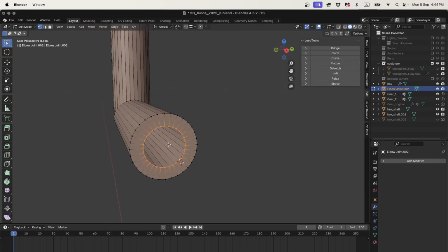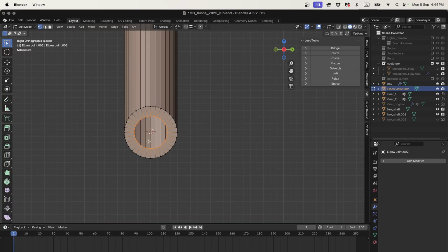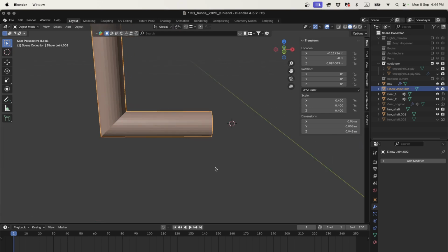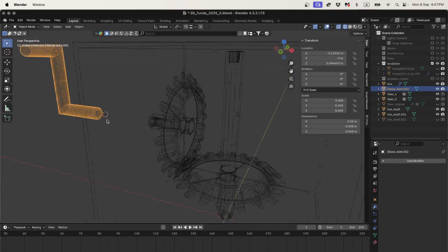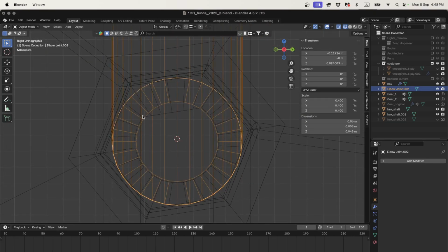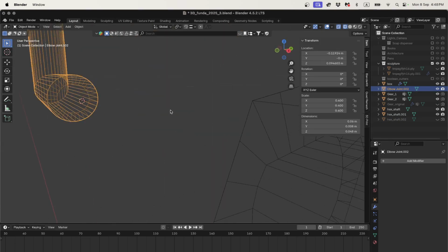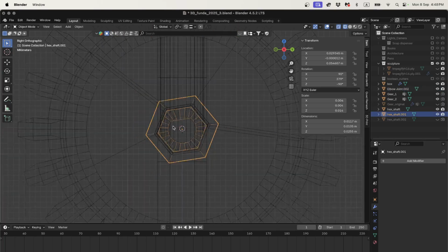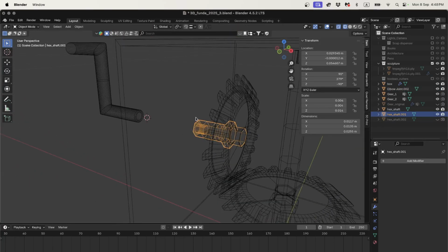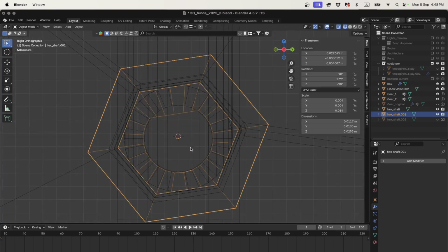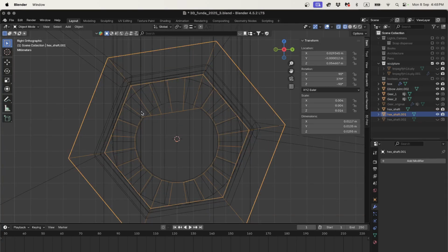Now here, we're going to do the same thing again. We're going to make that D shape with 7, I'll have to check, hold on. Okay, then I'm going to just look down the x-axis, and we need to match up this little D socket with the shaft that we want to make here. It's pretty easy, bit of a fiddle, but it's not too bad. So this is our hex sort of pin here, and if you remember, we rotated everything by 9 degrees so that the teeth would mesh here. So I just want to get rid of that 9-degree rotation so that we're looking flat down the axis and we can use our transform tools properly.